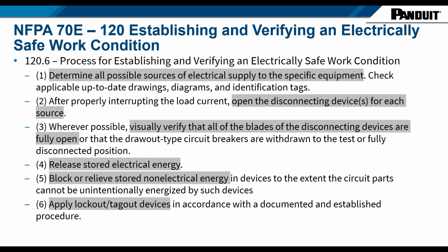You should look and see if they've opened, because sometimes they do stick, and that's one of the failure points of this, and that's why we have absence of voltage testing: sometimes those disconnects do stick closed. Something fails in them, they're mechanical devices. So if you can visually inspect it, great, visually inspect it.